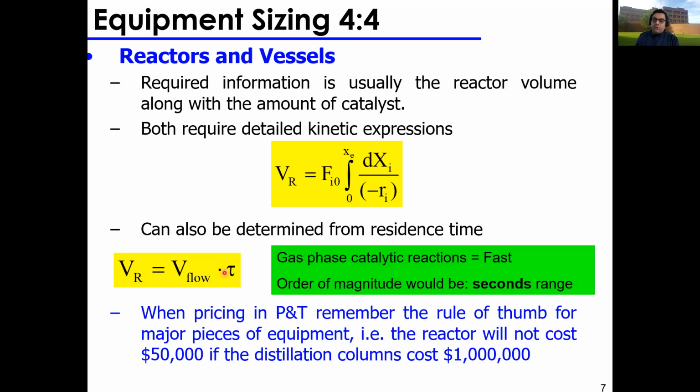So, for example, if you have a solvent in a stripping column, and you only have a small amount of solvent. It's a very expensive solvent, very small amount of solvent, and you know that this solvent can only stay in this column for 15 seconds, maybe 1 minute, and then I need it to get out and to be recycled. Otherwise, my process is going to dry out, and my distillation column is going to crash, right? So you already know the residence time. You can get the volume from there. However, for most cases, you just use your basic design equations to do that.